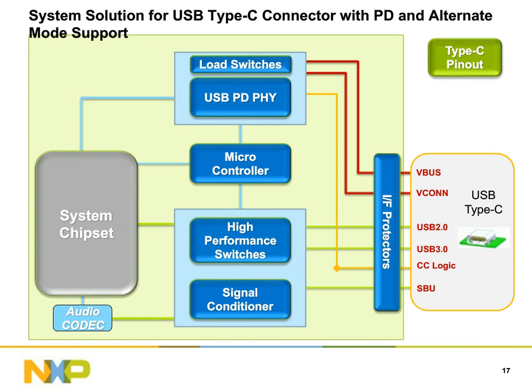So essentially, to recap, you have your PD5 and MCU combination that will take care of your power delivery implementation and messaging. You have load switches for your port protection and any faulty overvoltage or current protection. You have your data switches to support the flippability of the connector, which is, by spec, the USB Type-C connector is flippable.